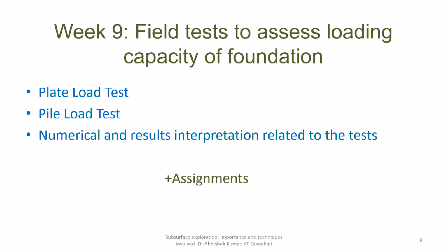Then pile load test and plate load test, these are very important tests whenever we are going for understanding the bearing capacity, whether for shallow foundation or deep foundation. For shallow foundation we go with plate load test, for deep foundation, particularly pile foundation, we go with pile load test. How these tests are done, what the codal provisions are, plus some numericals we will be discussing, so that we can understand the rate at which loading has to be interpreted while analyzing the records from the site, plus some assignments will be there.